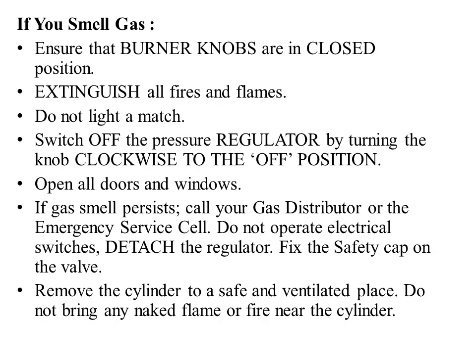Next, what has to be done when there is a leakage? Of course, when you smell gas, which means there is a leakage, these are the steps that have to be followed. First of all, we should make sure that the burner knobs are in the closed position. We should extinguish all fires and flames. Do not light a match, of course. Switch off the pressure regulator by turning the knob clockwise to the off position.